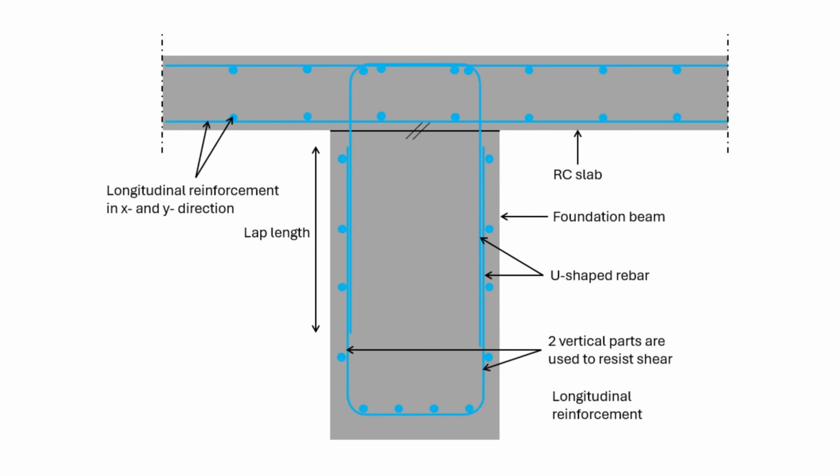Another example is if your beam is very tall, it also makes sense to split up the closed stirrups into two U-shaped rebars to account for tolerances. In one of my projects, the foundation beam was almost 2 meters tall. Imagine having to bend a closed stirrup that is 2 meters in height, precisely as the rebar schedule says.